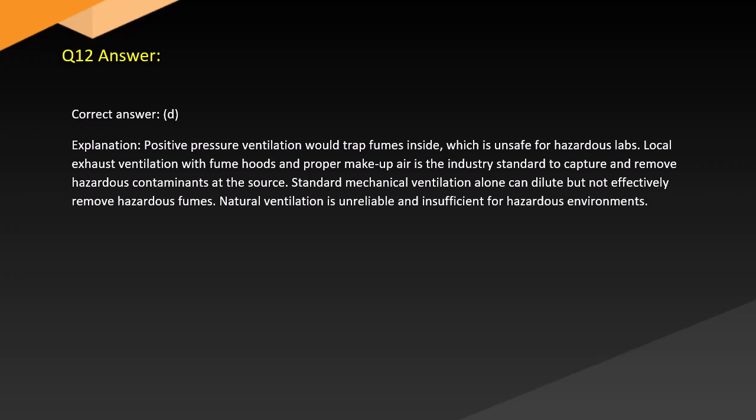Answer. Correct answer, D. Explanation. Positive pressure ventilation would trap fumes inside, which is unsafe for hazardous labs. Local exhaust ventilation with fume hoods and proper make-up air is the industry standard to capture and remove hazardous contaminants at the source. Standard mechanical ventilation alone can dilute but not effectively remove hazardous fumes. Natural ventilation is unreliable and insufficient for hazardous environments.